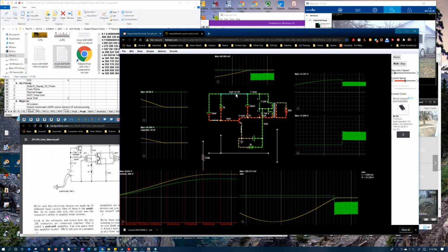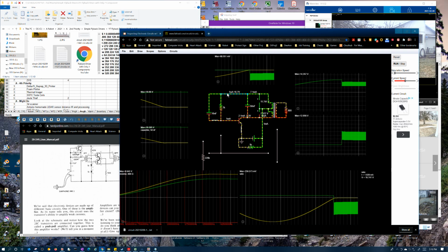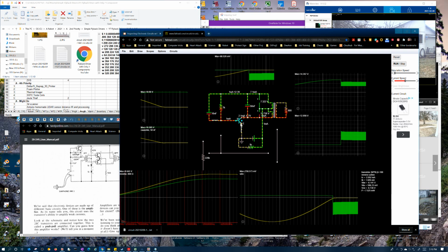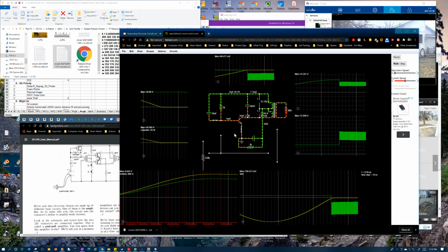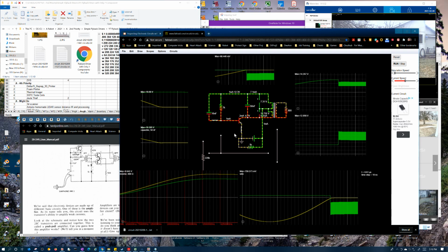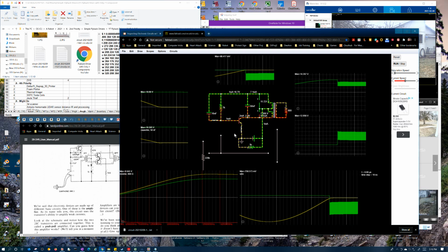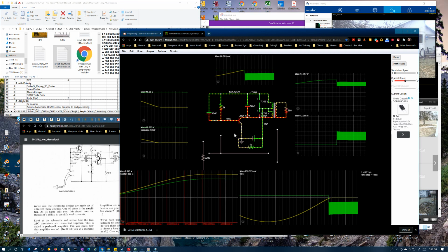The whole while it will be causing this voltage to drop below the threshold of this transistor, turning it further off by making it a negative going signal, which could be a problem because a lot of transistors can only stand so much reverse voltage across the base emitter. I believe that's an actual rating in a data sheet. This reverse voltage withstand capability.